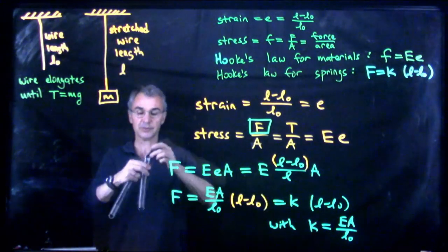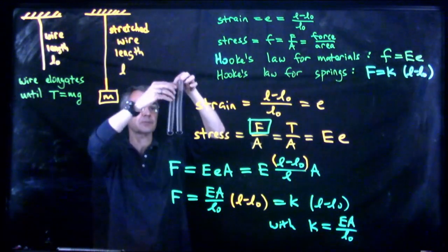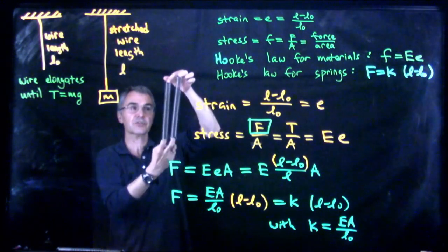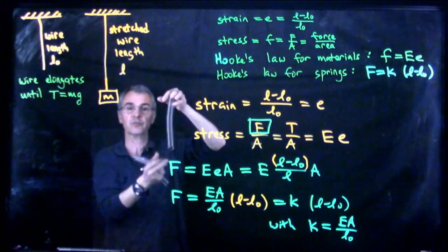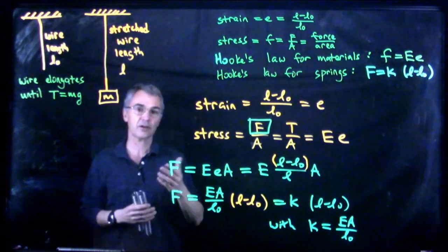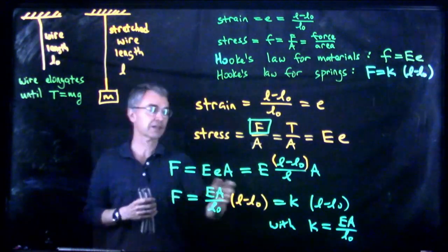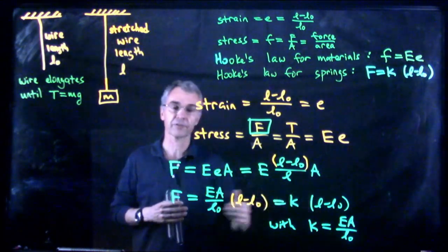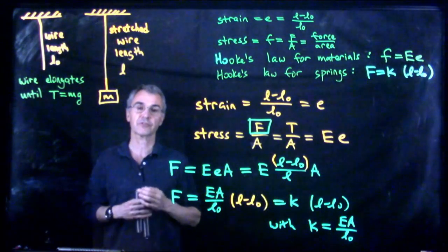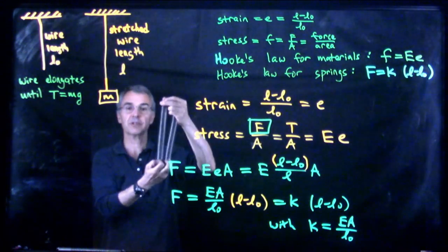And then another thing we'll see at some point is if you take 2 ordinary Hooke's law springs and you stick them side by side, then the resulting spring constant, if the springs are identical, is twice the spring constant of one spring by itself. And that also sort of makes sense because if you take these 2 pieces of material and put them side by side, their cross-sectional areas are adding up. Like the cross-sectional area of the 2 things side by side is just the sum of the 2 cross-sectional areas. So it turns out if you put 2 springs side by side, their spring constants add.